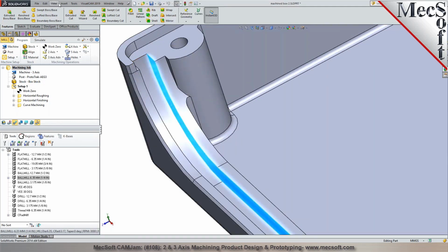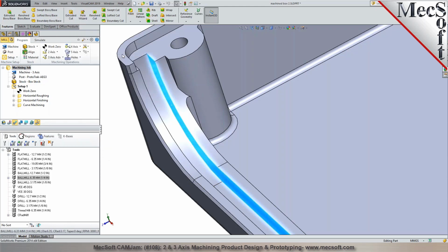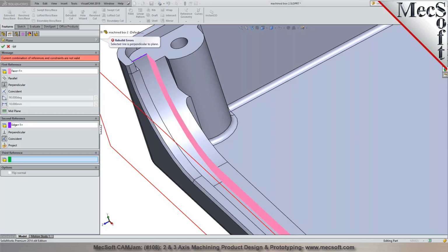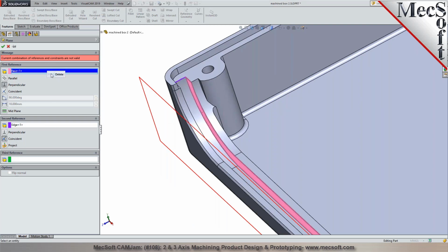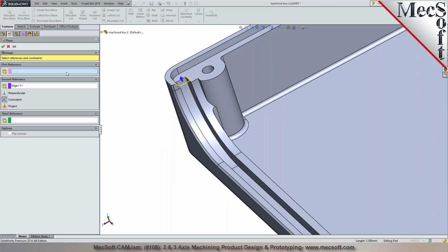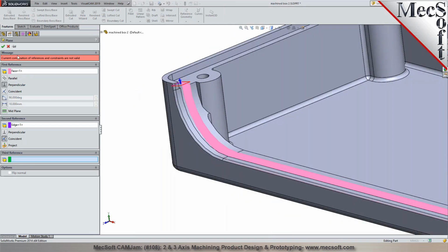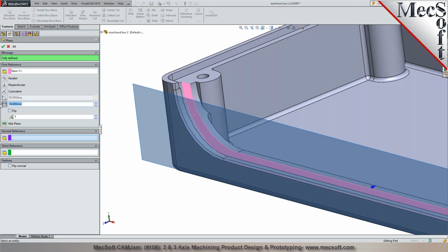So I'm going to use this face and insert a reference geometry in SOLIDWORKS and create a reference plane. And I will specify a distance in here. So I'll measure this distance. I'll say clear the selections. So I want to pick the first reference as this face in here, right? I could do a plane with that face right here and then give it a distance. Insert a reference geometry, a plane, and then I split the difference in here.